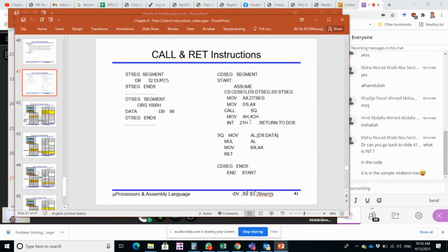It's giving an interrupt. It's interrupting the microprocessor to exit your code. This is actually an indication for where your code is finishing. As you see here, it's returning to DOS. We are not using DOS anymore, so it's an old-fashioned way to finish the code. By the way, it is still used, but now in a more elegant way for the programming. But you don't worry about that right now. We will explain that in the interrupt chapter, inshallah. Agree?